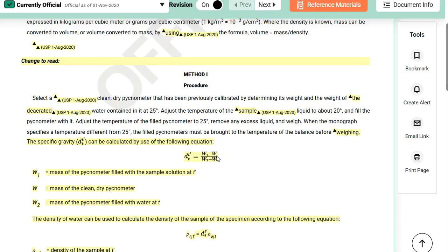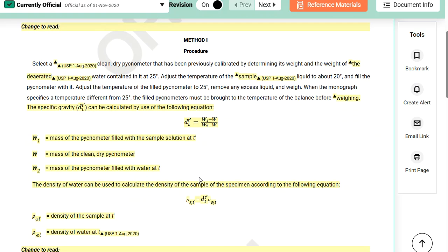But by definition, and by what you've been told in other science courses, yes, you can take the density, divide by the volume of each one of those, and then divide those densities with each other and get specific gravity too. It's extra work, it's extra steps, and you're using the same pycnometer, you should be at least anyway. So this is going to be a shortcut to calculate that value for you.